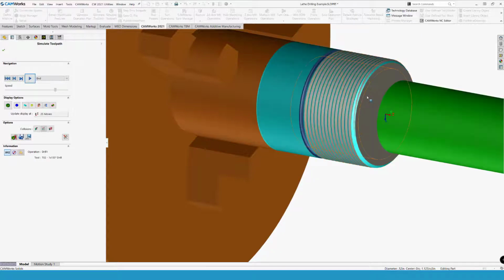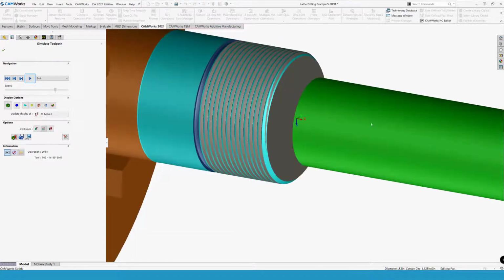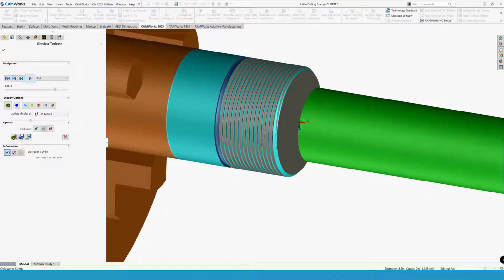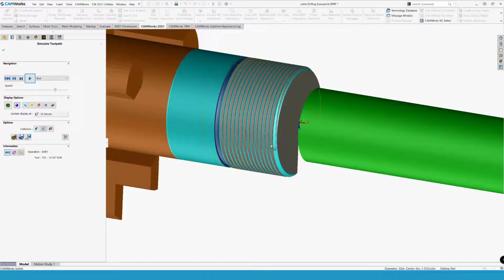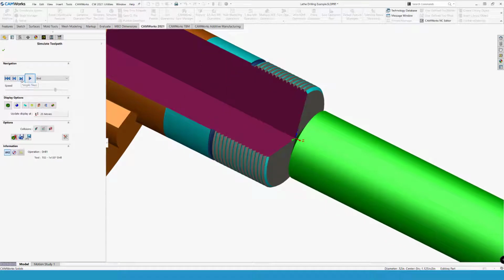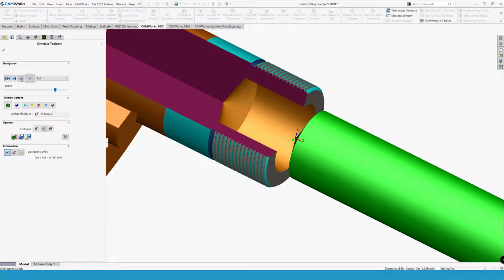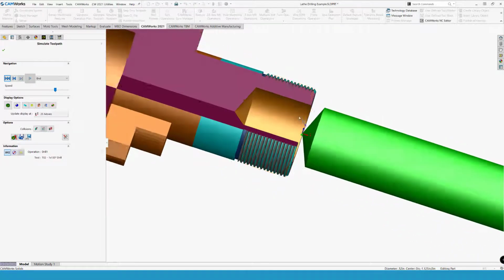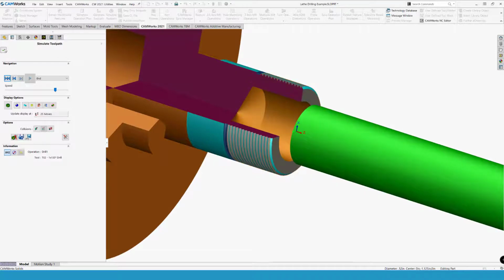And thread is always going to take some time to calculate in that scenario. But here we have the 1 inch drill, and I could probably go in and say half, let's go 3/4, that is more pretty. And then just single step this one. So now we drill in and retract, and that's it. So you got the 1 inch drill coming into that depth.